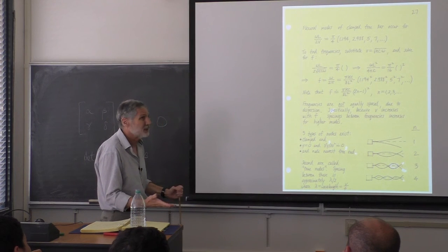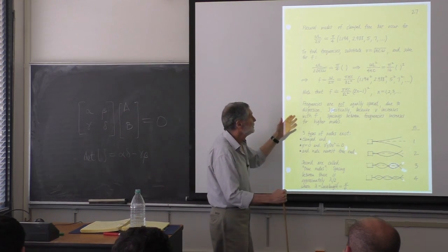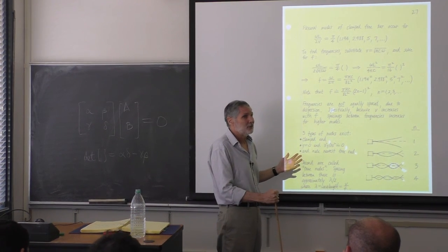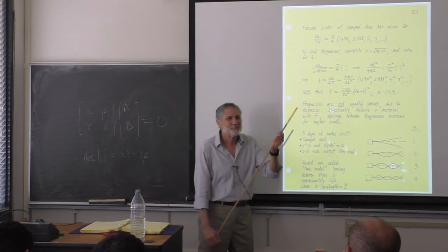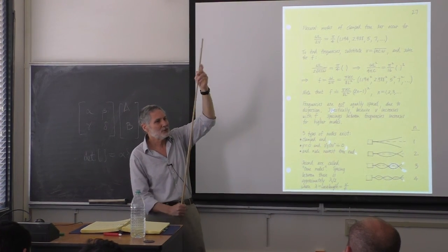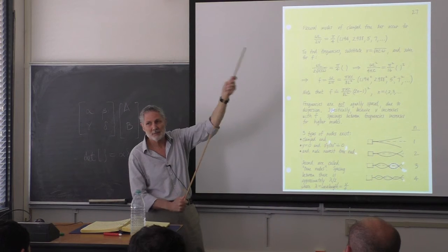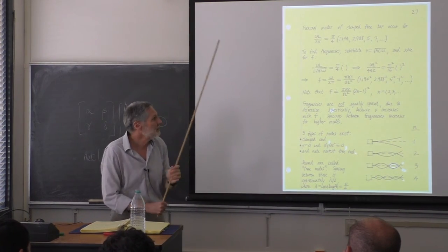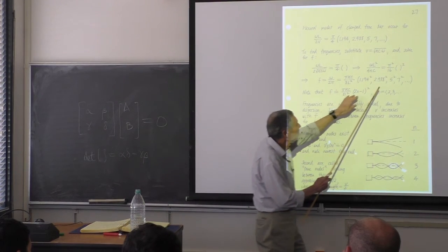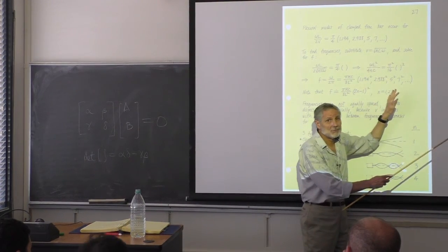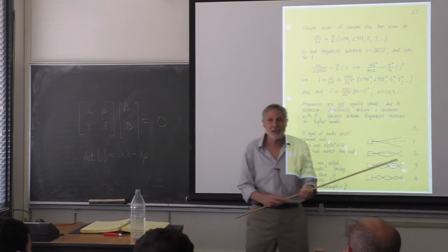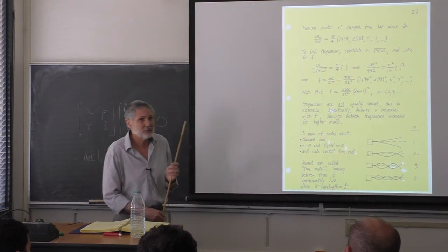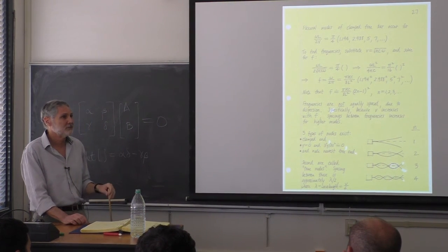So that has consequences. For example, an earthquake is going to excite a number of these flexural modes of a building. And those modes get farther apart in frequency. It means they're going to be harder to excite. So it'll tend to be more of a pure tone.